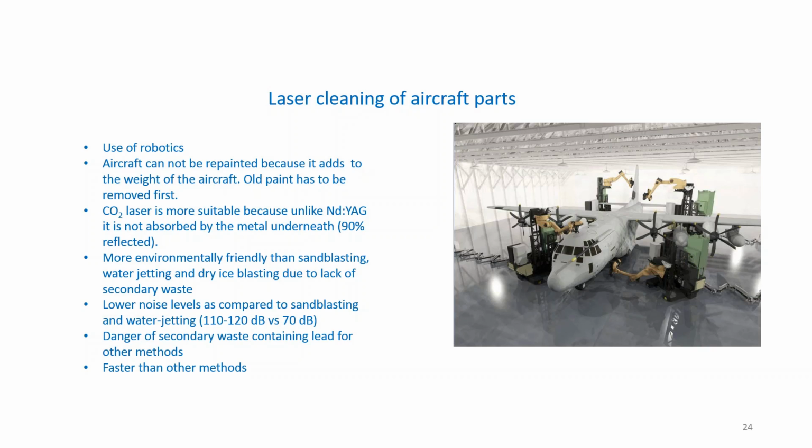Then CO2 laser is more suitable because, unlike neodymium YAG, it is not absorbed by the metal underneath. 90% is reflected. Then the laser technique is more environmentally friendly than sandblasting, water jetting, and dry ice blasting due to lack of secondary waste and lower noise.